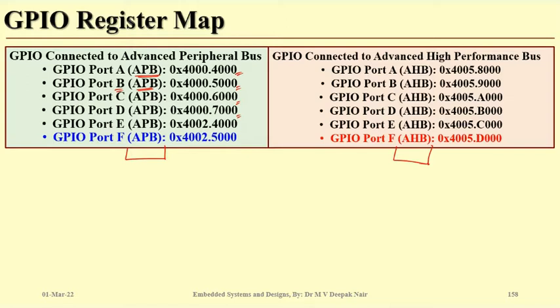Whichever peripheral you are going to use, you must first check whether that peripheral is supported by this bus or not. For that, you can go and check the architecture or the bus diagram or bus matrix of the microcontroller.